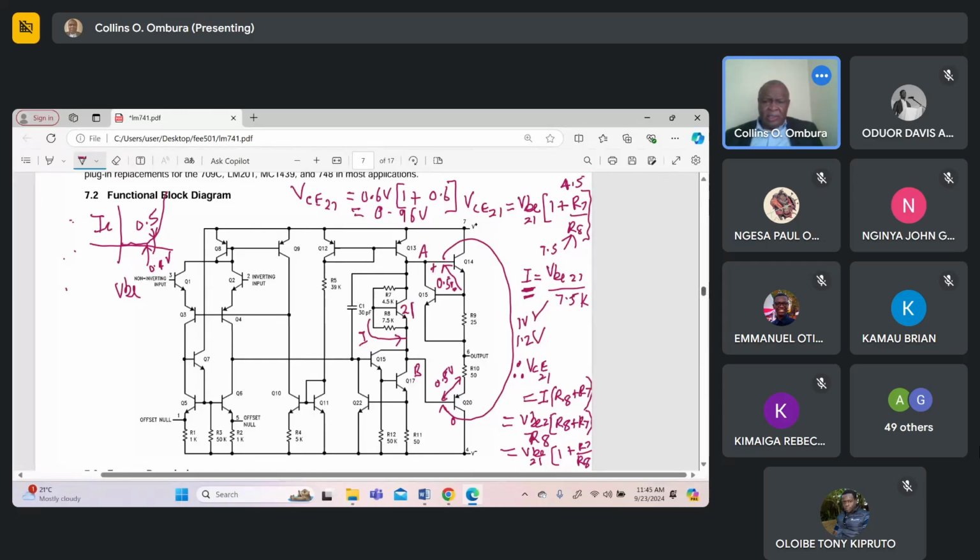Okay. Now, the interesting thing of this circuit is that, remember this VBE, this outside is 0.6 volts over here. When the temperature increases, it decreases. When the temperature decreases, it increases. The various curves, let me draw on the left over here again. So if this is a temperature, say T1, this is a temperature, say T2, and in this case, T1 is greater than T2.